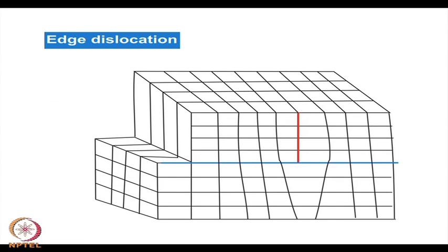With this background, let us try to see what a dislocation actually is. Dislocation is related to the deformation of the crystal, specifically plastic deformation. It is a permanent deformation where the dislocations come up. For elastic deformation, where there is no permanent deformation, there is no question of dislocations being formed or needed. The concept of dislocation is irrelevant there, whereas for plastic deformation, the concept of dislocation is very, very important.